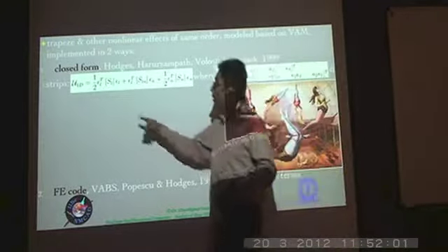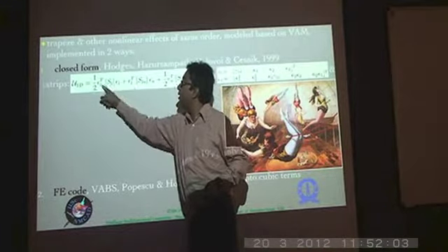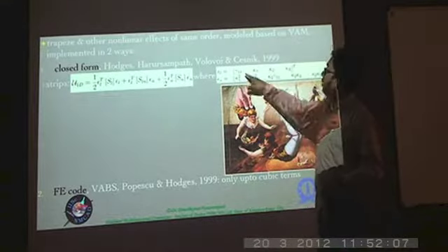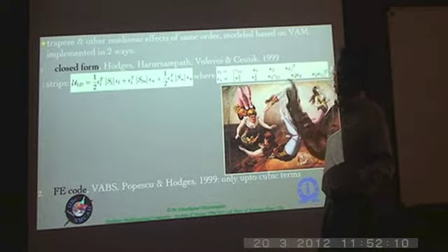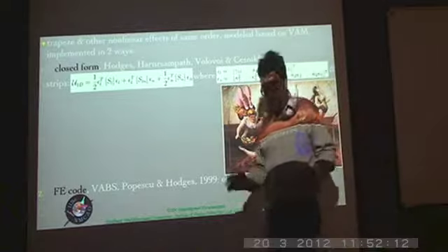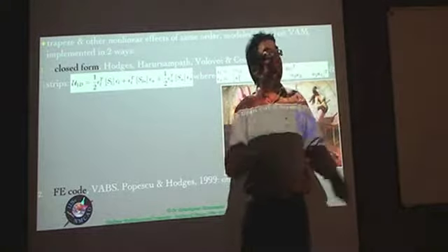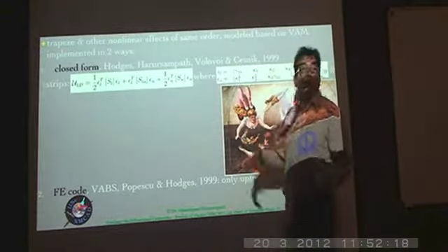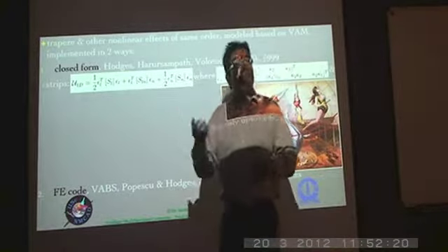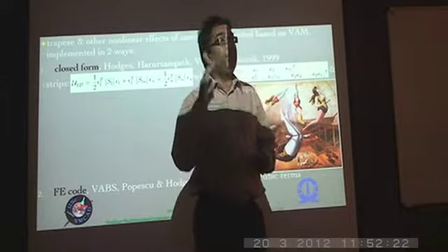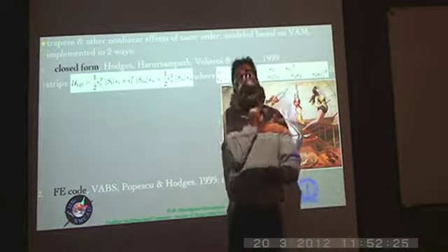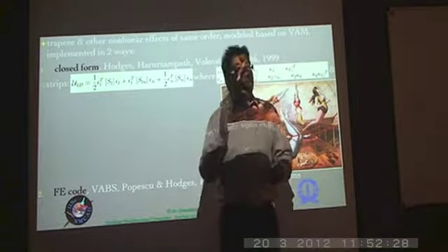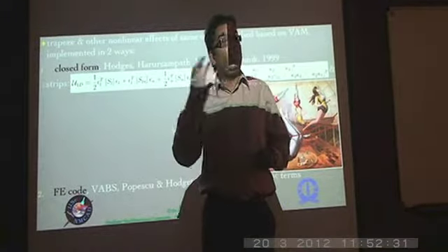Now, the vector which is multiplying here is epsilon L, which is our standard thing that we look at, which is gamma 1, kappa 1, kappa 2, kappa 3, which of course, consistent with the notation that I was talking to you about earlier, should actually have bars. Because here it is a thin strip, and in a thin strip, the contribution to the energy of the transverse shear strains, namely gamma 1 alpha, or what we call gamma 12 and gamma 13, is very small.